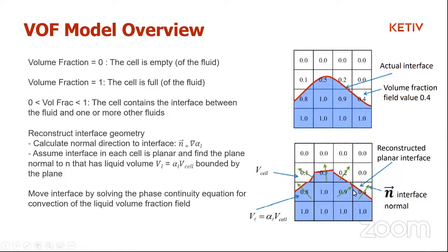And this is being reconstructed as and when the solution keeps solving. Mostly VOF simulations are unsteady in nature because we are tracking the shape of the interface over a course of time. And in those situations, as the time steps progress and the conservation equations keep getting solved, this boundary changes dynamically depending on the values of the volume fraction and the different forces that are acting on the phases. So hopefully this gives you a basic understanding of how the VOF model goes about tracking this interface, this boundary that exists between different phases.